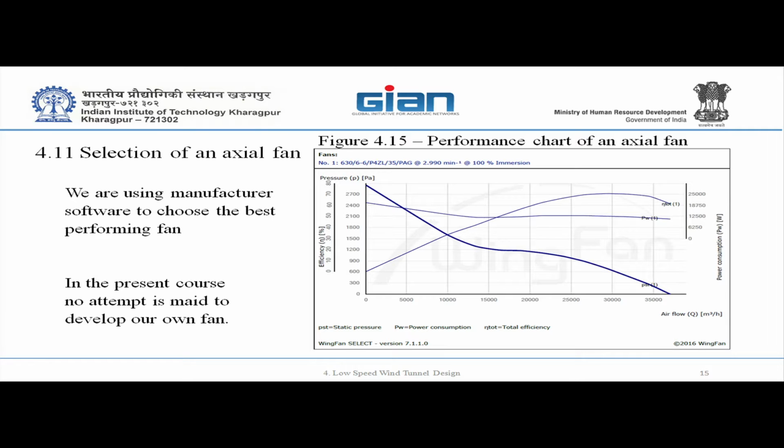You can get into this manufacturer's website where you insert your details and information, and it comes out with a lot of selections of fans. You just have to put in your working point, and according to that, you choose your fan.